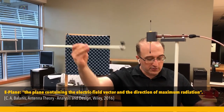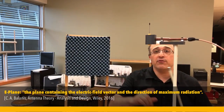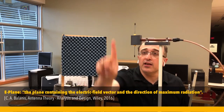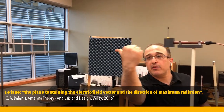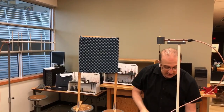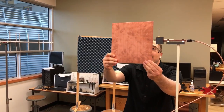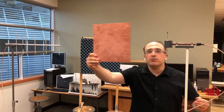And we also know that the electric field of this dipole antenna is along this direction. So now we're going to make a plane with these two vectors. That's the direction of maximum radiation, and that's the direction of the electric field. Therefore, we have a plane consisting of these two vectors, and that's essentially my E-plane cut.